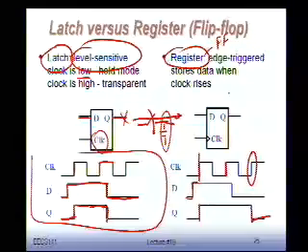Okay? Infinitely fast type of functionality. This is called a positive edge-triggered flip-flop because it works on the positive edge of the clock. I could also have a negative one, something that basically works on the low-going transition of the clock. You can choose. It doesn't make a difference, it's just an inverter. That's the only difference I really have.